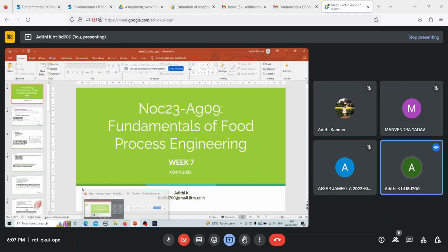What happens in freezing is, let's say, the similar diagram that I showed you here. If you have a block here, you're removing heat from two different directions, from this side and from this side. You can see that this dark orangish region starts becoming ice, and your liquid product is in the middle. So whatever heat removal needs to happen has to come from your inner unfrozen layer through the ice and then to air. This is how freezing happens. So heat is removed through the ice block. You have an ice deposition here, and whatever heat is being removed has to pass through this ice.